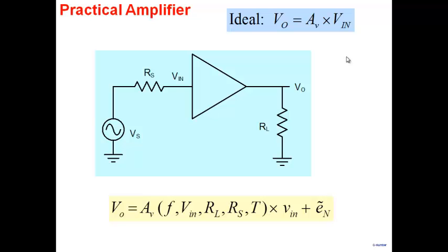No. You have emphasized one frequency over the other. In some sense, you're causing a distortion. Right? So you don't want the gain to be a function of frequency. You want gain to be independent of frequency. But all amplifiers have a dependence of gain on frequency.